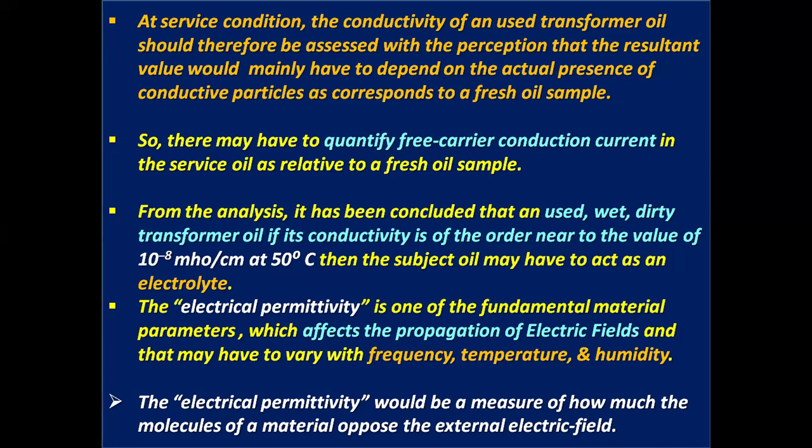From the analysis, it has been concluded that a used, wet, dirty transformer oil, if its conductivity is of the order near to the value of 10 to the power minus 8 mho per centimeter at 50 degrees centigrade, then the subject oil may act as an electrolyte.